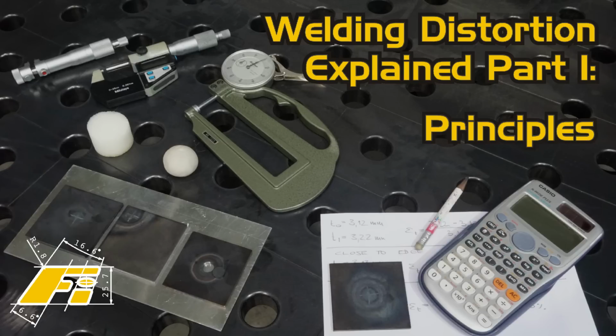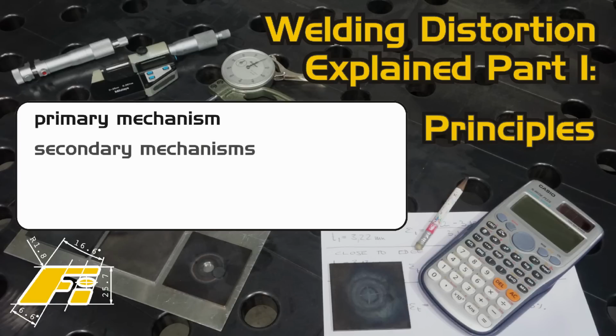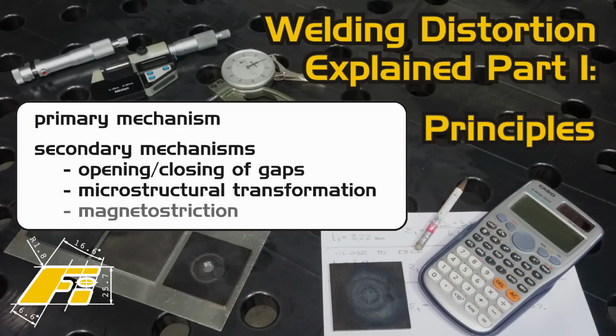But don't worry, the contents are tailored for practical people like, I guess, you and myself. Welding distortion is thermally induced and after cooling residual distortion of a workpiece. It is driven by a few individual mechanisms which we will distinguish according to their impact as primary and secondary. The primary mechanism of welding distortion is subject of this video series. Secondary mechanisms are, for example, opening and closing of gaps during welding, microstructural transformation or magnetostriction. The last two, however, in most practical cases play an insignificant role.